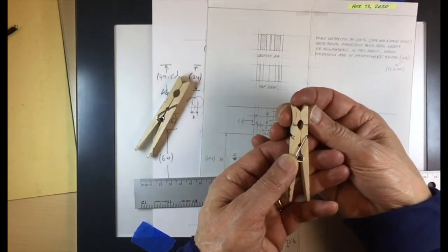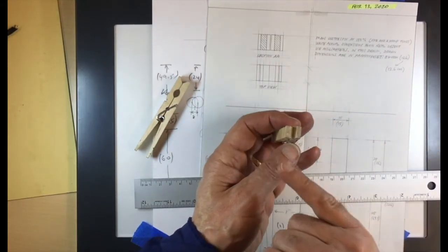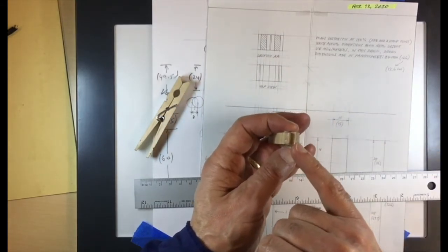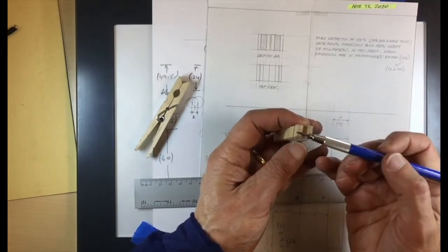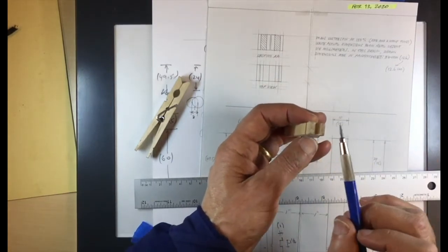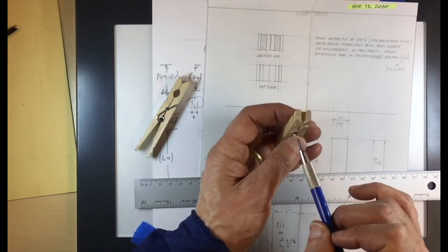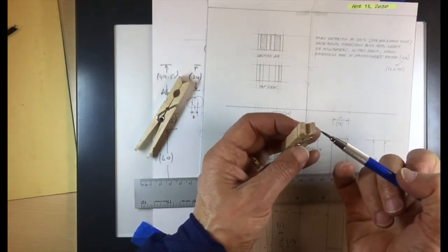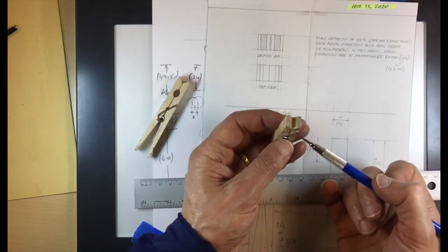And we etch the part that we cut through. So whatever is cut through, we etch, and that's the true section. Whatever is beyond is actually still an orthographic because those are not cut parts. They're real parts. So the lines should be, as you can see, regular lines, and this part represents what you can still see.